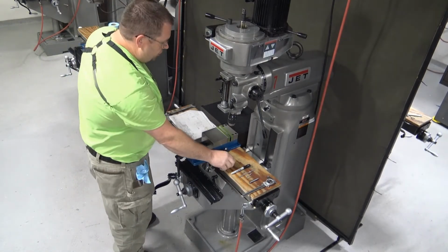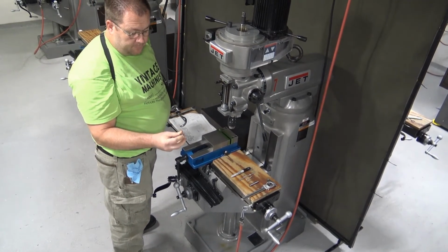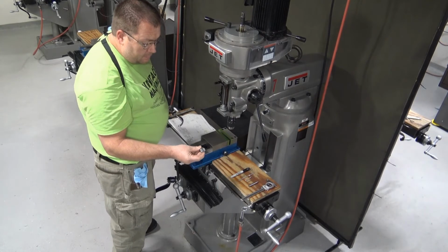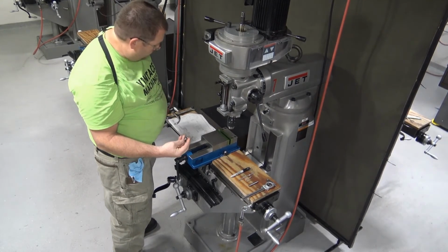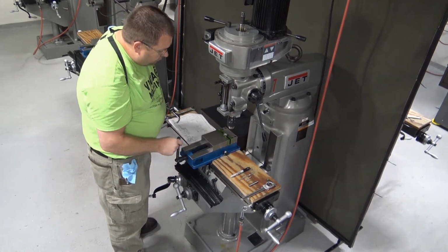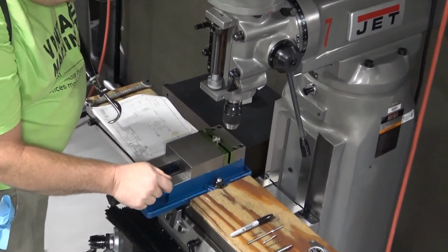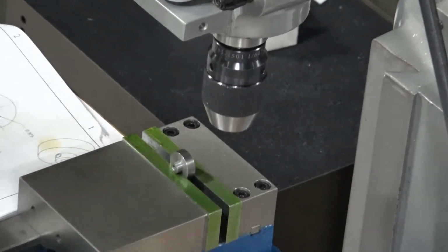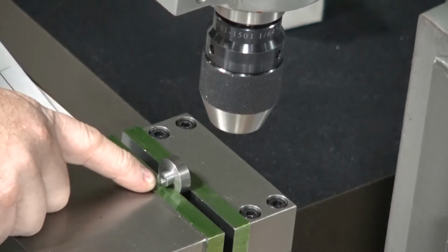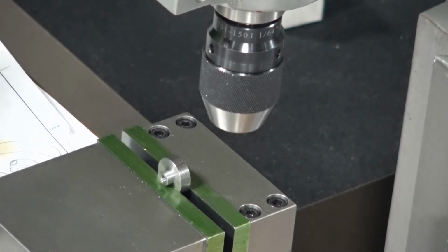So here we are in the machine shop, and the component that we're going to work on first is going to be our flywheel. We're going to finish that guy up here in pretty short order. The only requirement left on the flywheel is to put that 6-32 tapped hole. I told you when we were at the whiteboard that fixturing that part is going to be relatively easy. Basically, we set the small cylinder on top of the movable jaw in the vise, and we clamp just the meaty section of the flywheel.